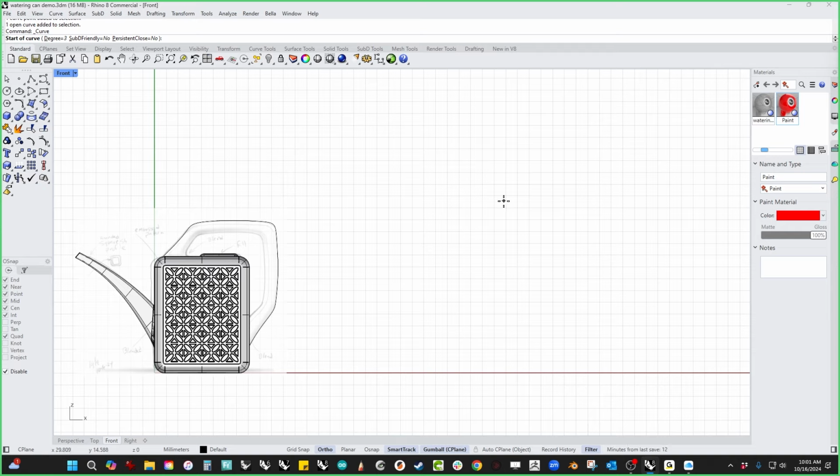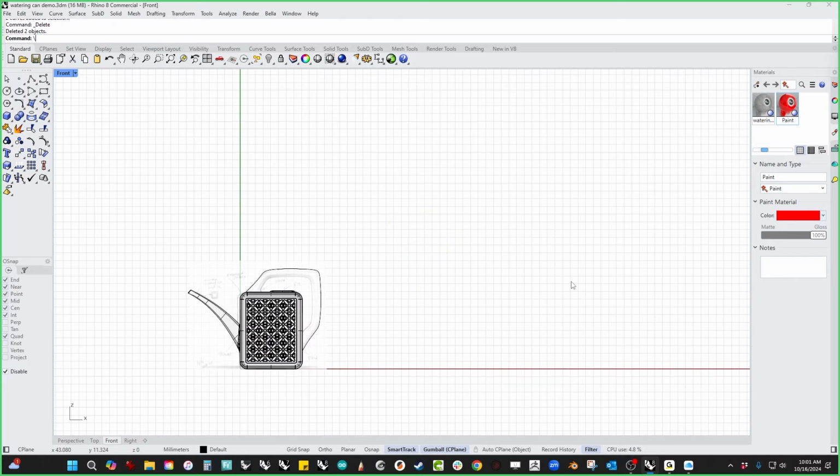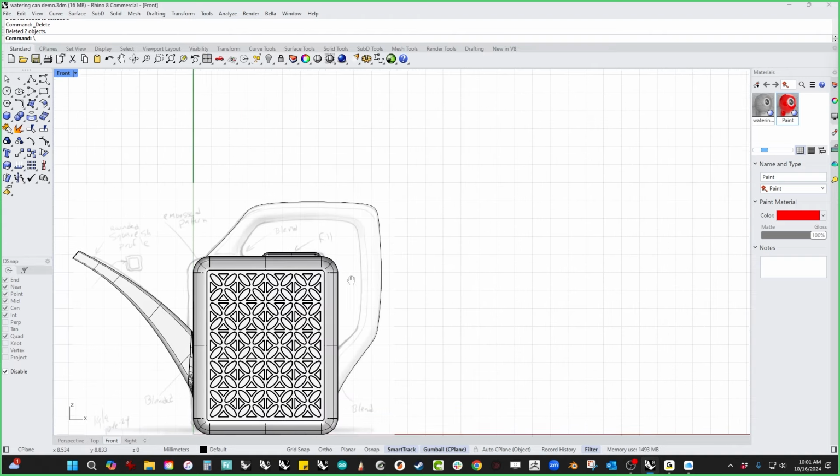And I always harp on this because it's important. Okay, because I always see people make corners like this. Right? No. 1, 2, 3. That's your corner. If you want it sharper, move the points closer. If you want it less sharp, move them farther apart. Okay? That's all it takes. If you keep that in mind when you're building stuff, especially if you're doing sub-D stuff, rule of 3 is massively important in sub-D. It'll make your life a lot easier.